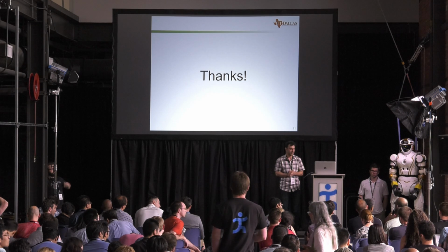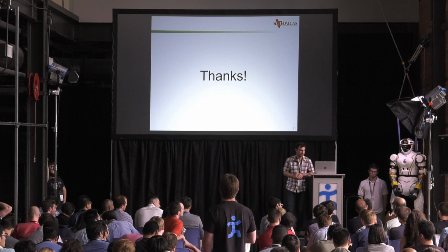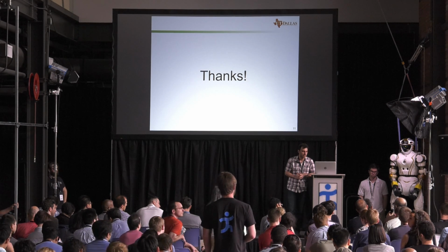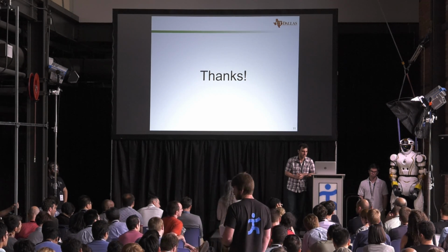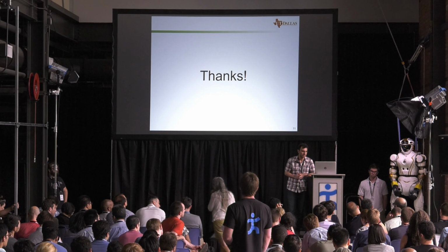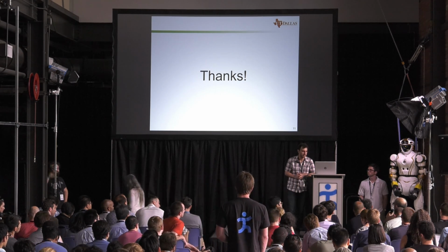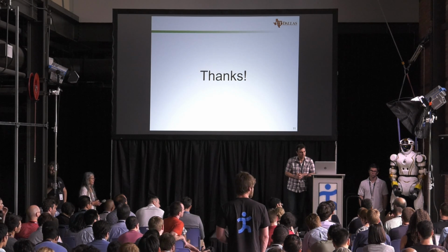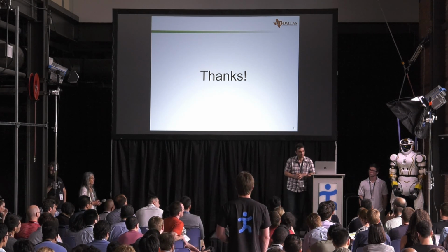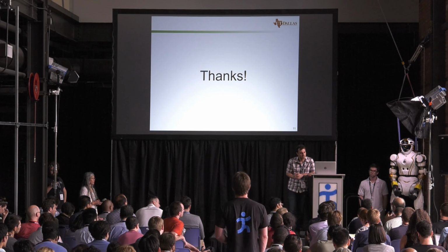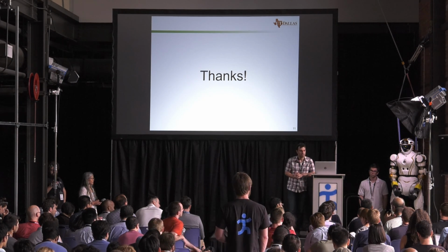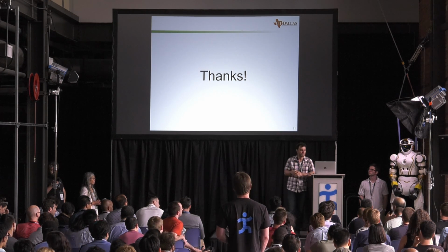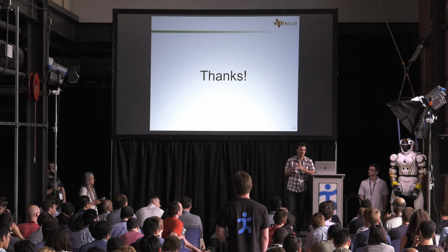Just a clarifying question. In the three-dimensional space of hip angle, knee angle, and ankle angle, you're restricting the motions to be some closed curve, and that's what you mean by holonomic control? Yes. And except for that you have a double-valued function, that's the same as hybrid zero dynamics? Double-valued function, what? For a given hip angle, there might be two knee angles, because you have some closed curve in the three-dimensional space instead of a single arc. Exactly. That's why it shouldn't be continuous. It should be a finite state machine.